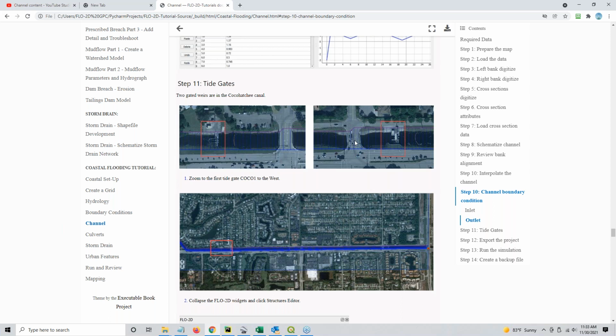Because this channel is so flat, there's not much slope in here and the water's moving really well, but because it's so flat, the downstream water surface and the upstream water surfaces across these bridge structures don't really change a whole lot. And there's not a whole lot of piers and stuff in here, and the water never gets up on the deck. Even if we give it that full discharge, it never gets up on the deck of these bridges.